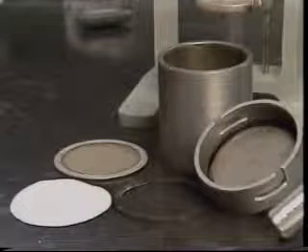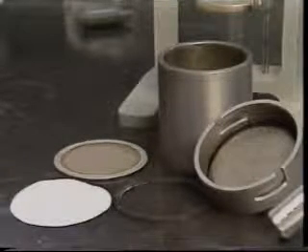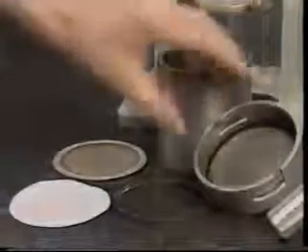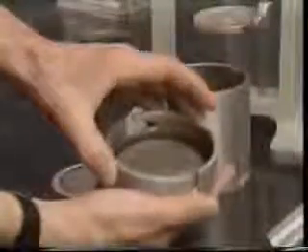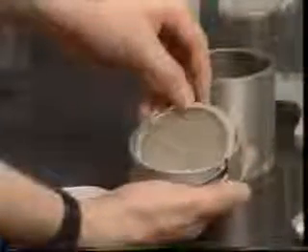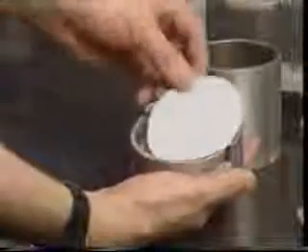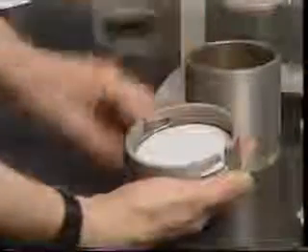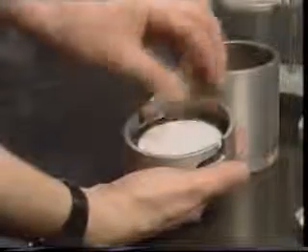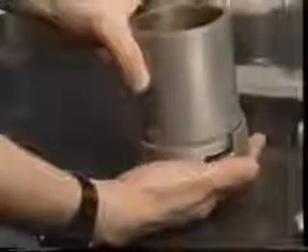The filter cell is removed from the frame and disassembled. All parts are inspected to be clean and dry. The rubber gasket is placed evenly in the base cap and the filtrate tube is checked for freedom from obstructions. Next, the screen is placed in the base cap and dry filter paper placed on top of the screen. A second rubber gasket is placed on top of the paper, followed by the cell body. The body is turned clockwise until it securely fastens into the slots.